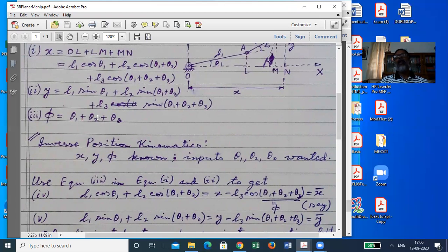Robot kinematics will always give you nonlinear equations and you have to solve them. You do not have to evaluate a function. The value of the function is known and you have to find out the value of the variable. This is the inverse which is difficult. Okay. So these things are known. You have to find out theta 1, theta 2, theta 3. Solution of equations. Nonlinear, coupled, fine.